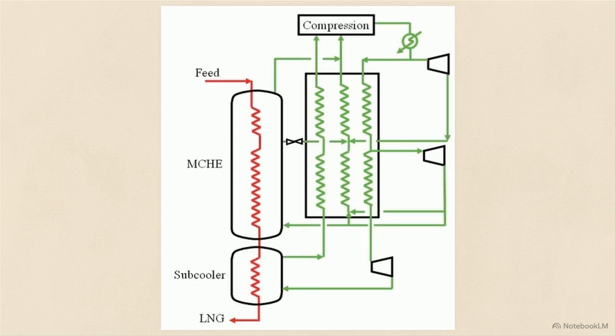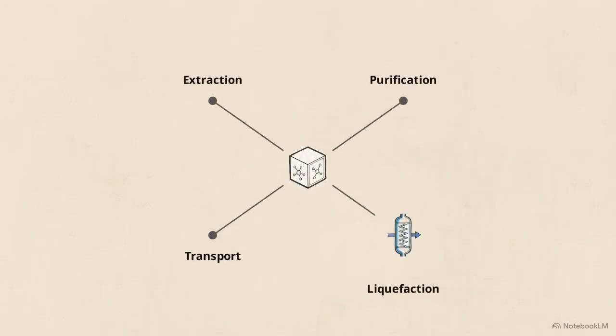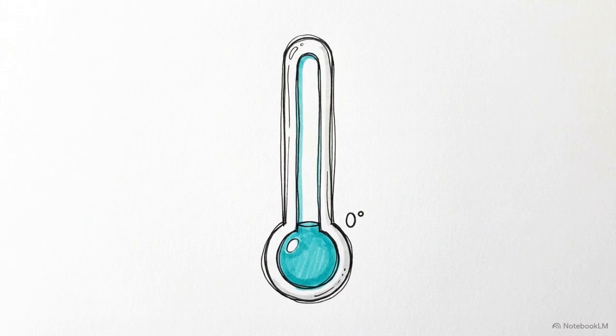For larger offshore facilities where storing highly flammable propane is too dangerous, engineers use an all-nitrogen recycle process. It relies on a complex series of turbo-expanders to create the necessary refrigeration without the heavy fire risk. Grab your teal marker. Trace the cooling paths on your drawing, mapping them to those refrigerant loops we just saw. Teal will represent all thermal extraction on our map.